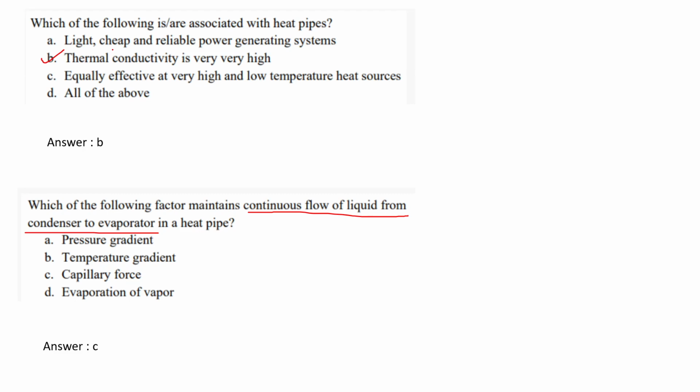So any other medium, but heat transfer and all. But one thing is, while you are designing a heat pipe, the capillary limit has to be considered. It should be much smaller, then only can the capillary limit be met easily. The bigger the size of the pipe, the capillary force will be less, very less. So it cannot take fluid from one point to another point.